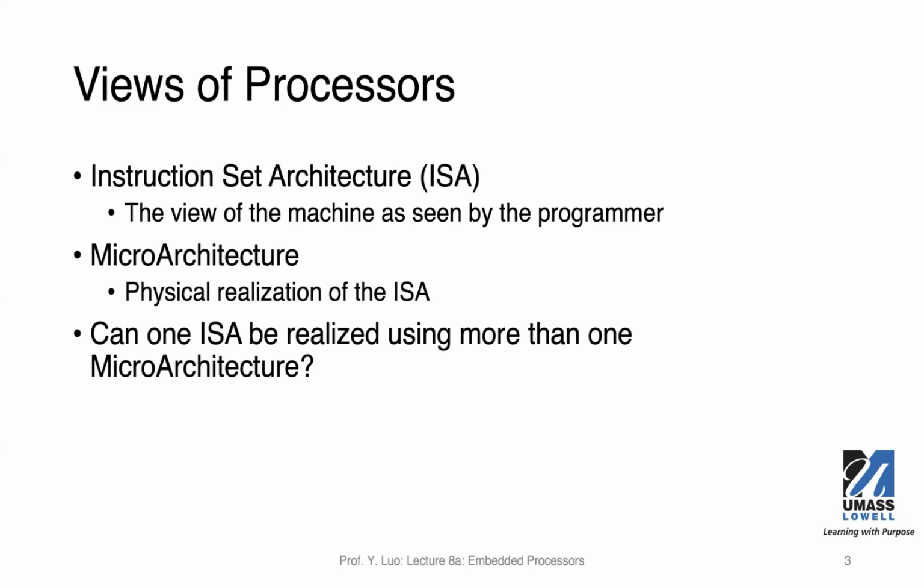These two boards actually use different processors, slightly different processors. But these two processors follow the same instruction set, this AVR instruction set. So the programs that you write, if you write in assembly language, chances are you can run the majority of the program on a different AVR processor.